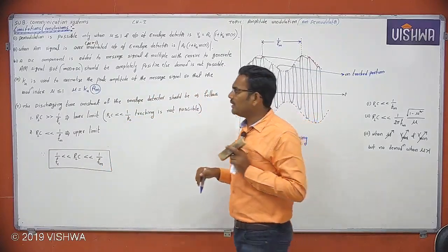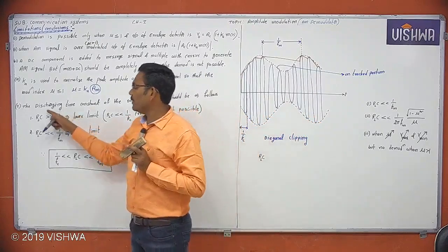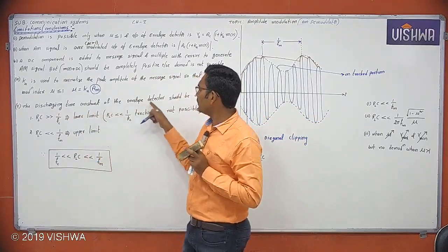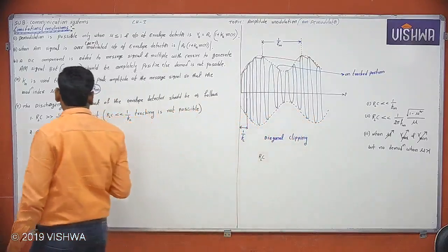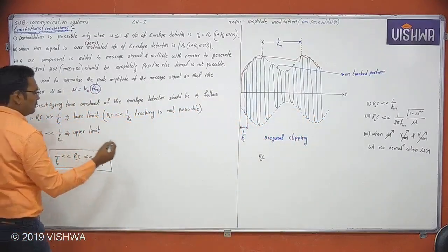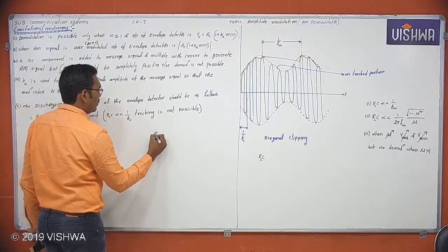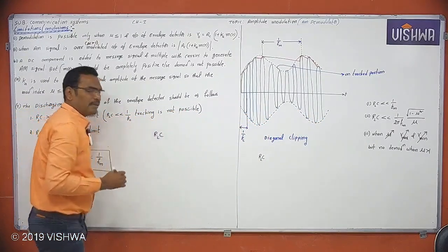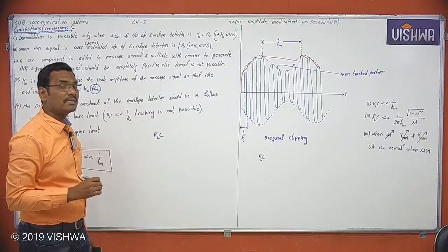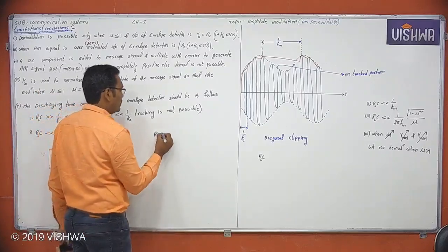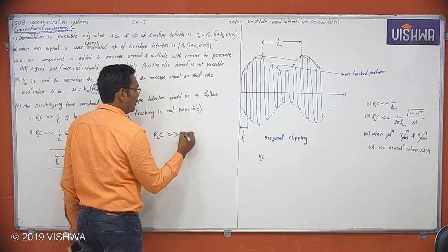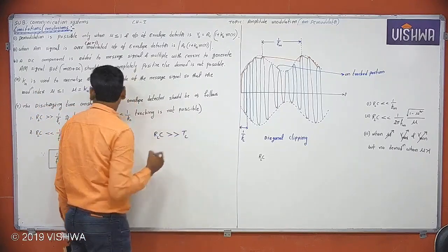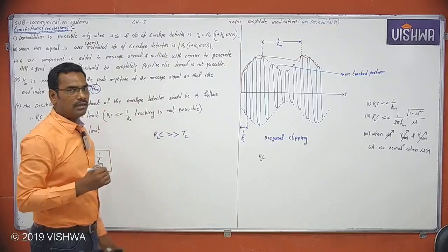The discharging time constant, RL into C, should be as high as possible, compared with the time period of the charging.